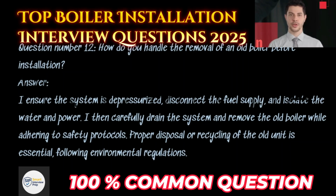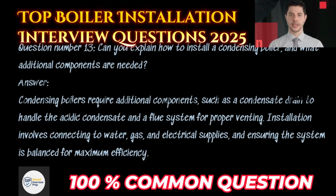Question number 12. How do you handle the removal of an old boiler before installation? Answer. I ensure the system is depressurized, disconnect the fuel supply, and isolate the water and power. I then carefully drain the system and remove the old boiler while adhering to safety protocols. Proper disposal or recycling of the old unit is essential, following environmental regulations.